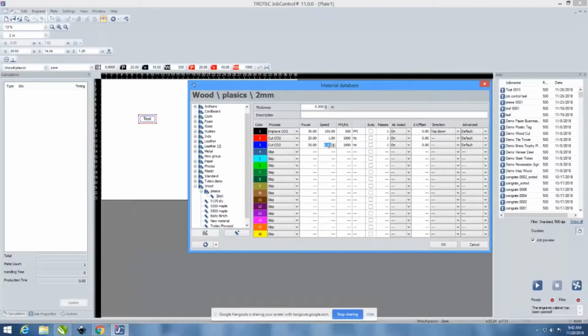The reason it's always a lower number is because it's a percentage of an extremely high number, being the engraving speed. For cutting through thicker materials, like maybe a 1/4-inch piece of wood, you'll often be less than 1. So on our machine here, 100 watt, we might be at 0.7 or 0.8% speed to get through a 1/4-inch piece of acrylic. It depends on the thickness, but for it to be fractional is completely normal as far as that percentage is concerned for cut speeds. Yeah, and you can go 0.75, 0.76, so you can adjust the percentage to that degree, and that usually helps with different cutting materials.